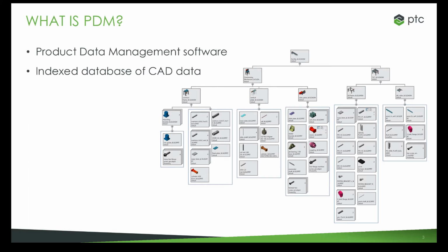The enormous amount of CAD data that is created, the multiple versions of different files, of part files, of assemblies, where are the references going? Which revision is this? PDM provides a way to help manage this, help keep it concise and clear. And what it is at its core is essentially an index database of CAD data to allow you an effective way to query it, an effective way to manage it and store it in a searchable, clear and concise way.